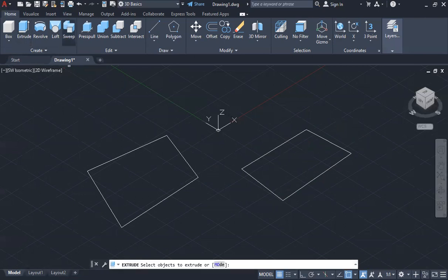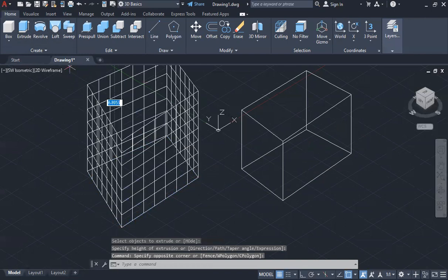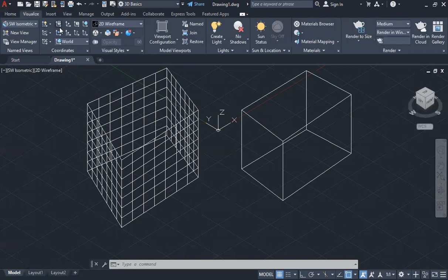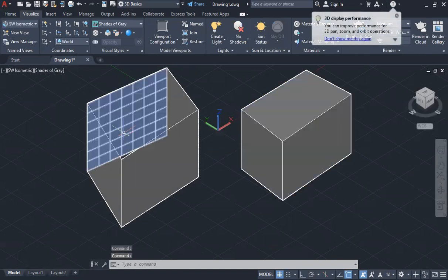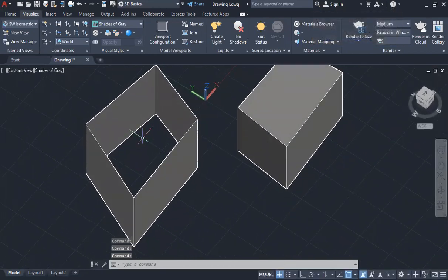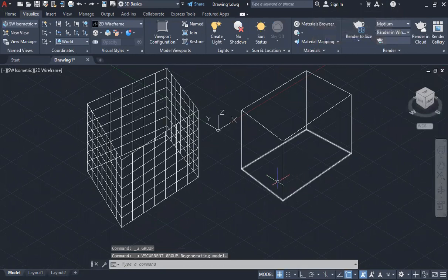So if I wanted to try and extrude, extrusion is basically just giving it a thickness. I can do that. If I try and extrude this, a whole bunch of different lines, it'll extrude as a surface. And this is not what we want for three-dimensional modeling. So if we change, say, our visualization and we look at it as a 3D solid, you'll see that this is a solid, whereas this is just a bunch of surfaces. Okay, it's not solid. So that's why we need to make sure our surfaces are all using closed loops.